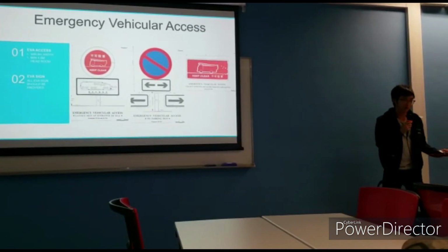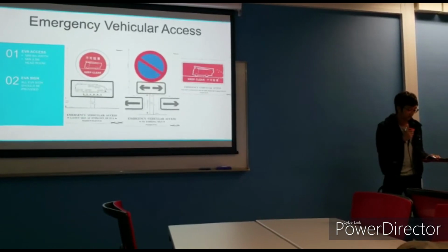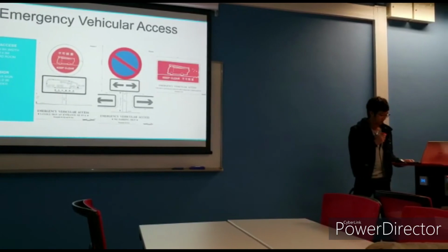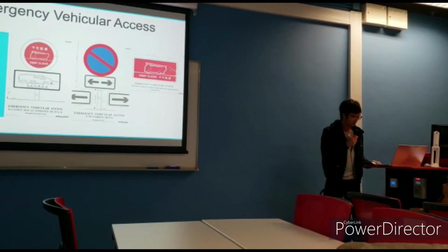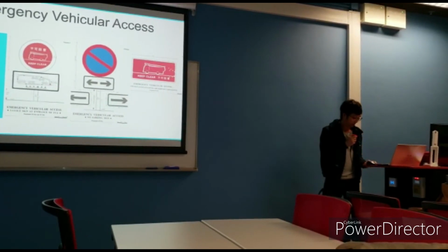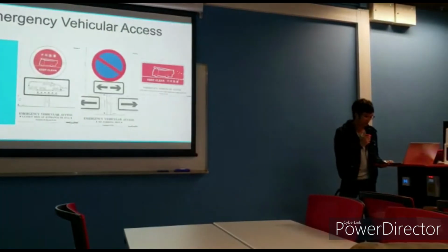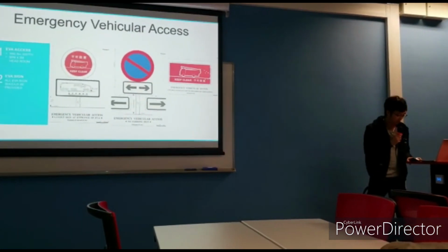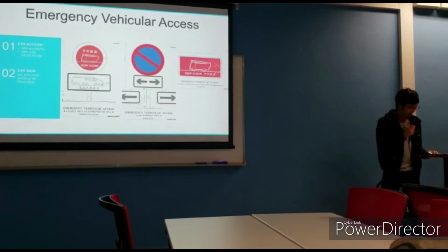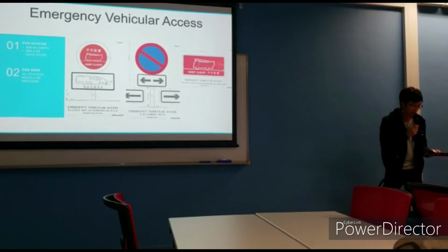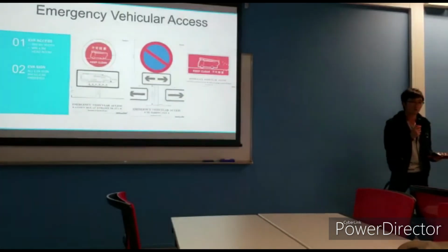For the emergency vehicle access, according to the code of practice for means of access for firefighting and rescue, the EVA should have at least 6 meter width and clear headroom of 4.5 meter height, and be formed by hard paved material. All types of EVA signage, crash gate and block plans showing the major facade of the building should be provided. If the structure is overhead on the EVA access, the EVA plan should show a sectional drawing with clear headroom of the structure.